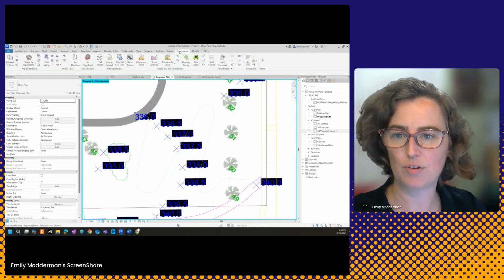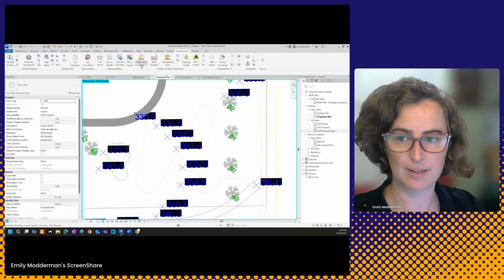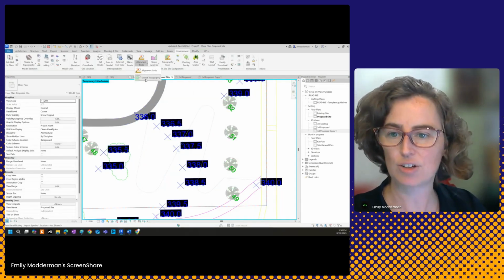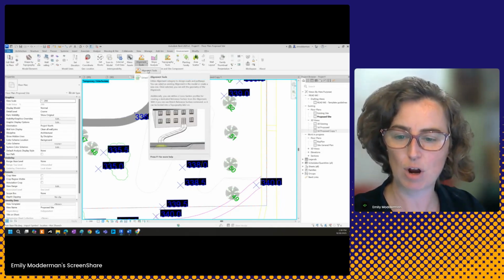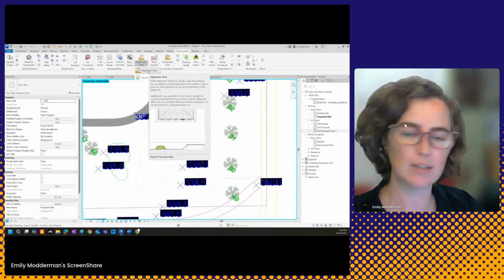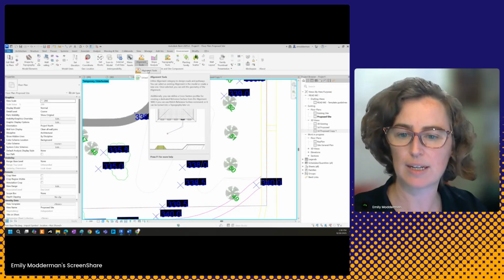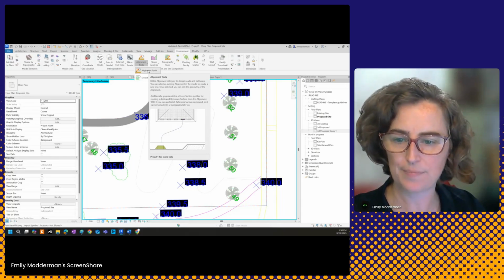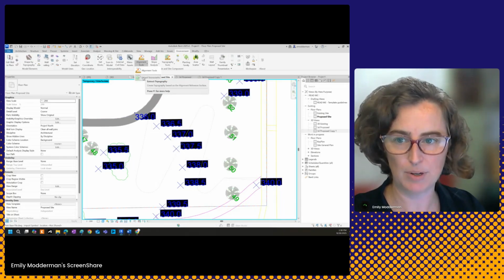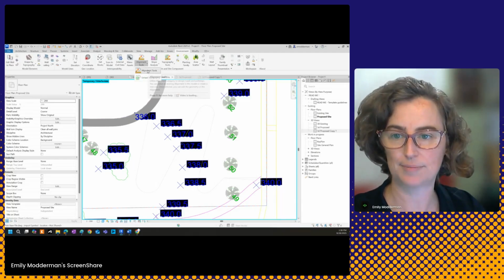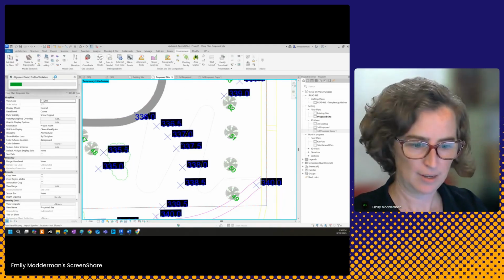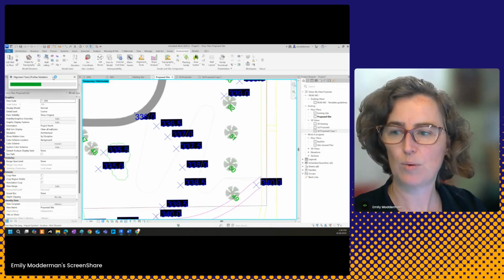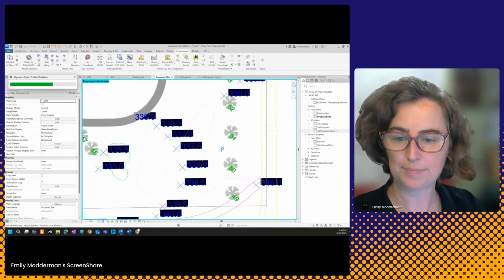And that's where the environment tool alignment comes in. So we've got alignment and extract topography. Alignment is going to help us draw our path and figure out our reference surface, our profile, like a cross slope or anything like that, like a road slope profile. And then our extract is going to build us that surface. So let's see what we do. All right. We've got our alignment tool loading up.